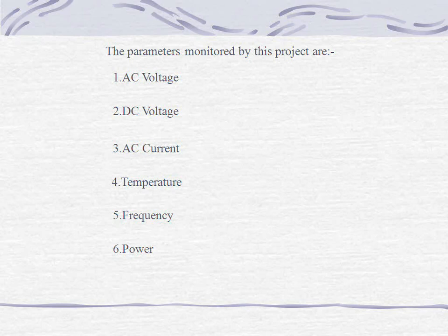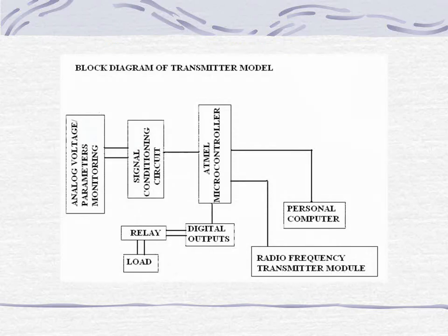This includes the problems encountered when adding renewable energy sources, how the protection should be done in smart grids, wide area stability, coordinated voltage regulation and angle oscillation damping, as well as the advantage of employing phasor measurement units and the GPS systems.